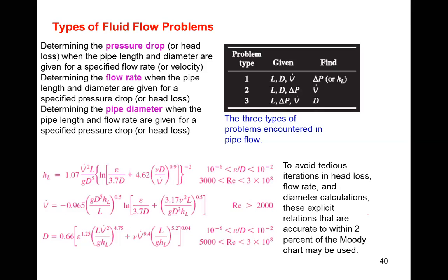Let's say you might have seen some pipeline or gas pipeline. Every 2 kilometers or 5 kilometers, you are putting a booster pump, a pump house. Why do we need it? Because in that particular length, your pressure drop would be there only because of all these frictional losses, changes in direction, bends, and those losses need to be compensated with the help of the pump. Otherwise, your fluid may not be able to flow to the other point, or sometimes the pressure will become too low, equal to the vapor pressure of the fluid, so that your fluid will convert to vapor and become gas.